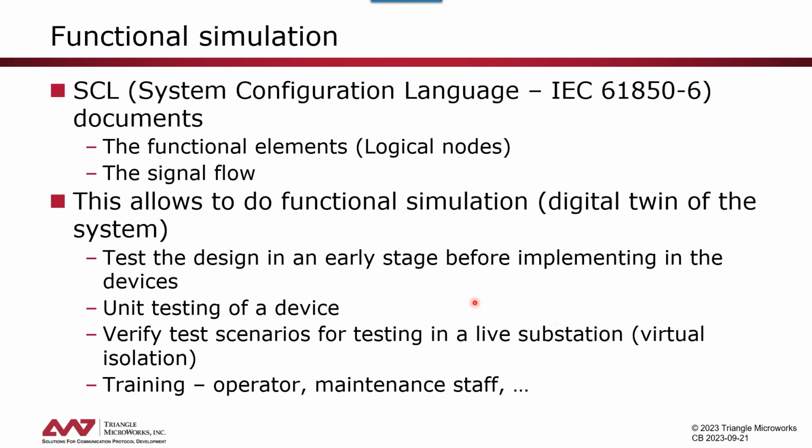Other use cases may be verifying test scenarios that you need to test in a live substation, the whole virtual isolation concept that IEC 61850 has. So you can on one side test these scenarios using functional simulation, but another opportunity is as well, as this involves a certain sequence that maintenance staff needs to do, you can also use the simulated environment to train maintenance staff.